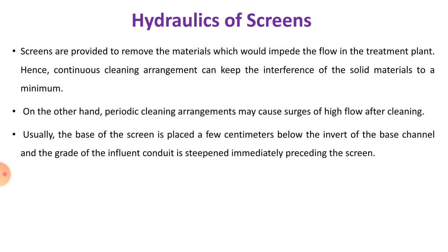On the other hand, a periodical cleaning arrangement may cause surges of high flow after cleaning. Now, it is also an important parameter that once the screen gets clogged, it should be cleaned periodically. But after cleaning, as all the pores or all the holes get opened, there may be chances of a surge of high flow after the cleaning.